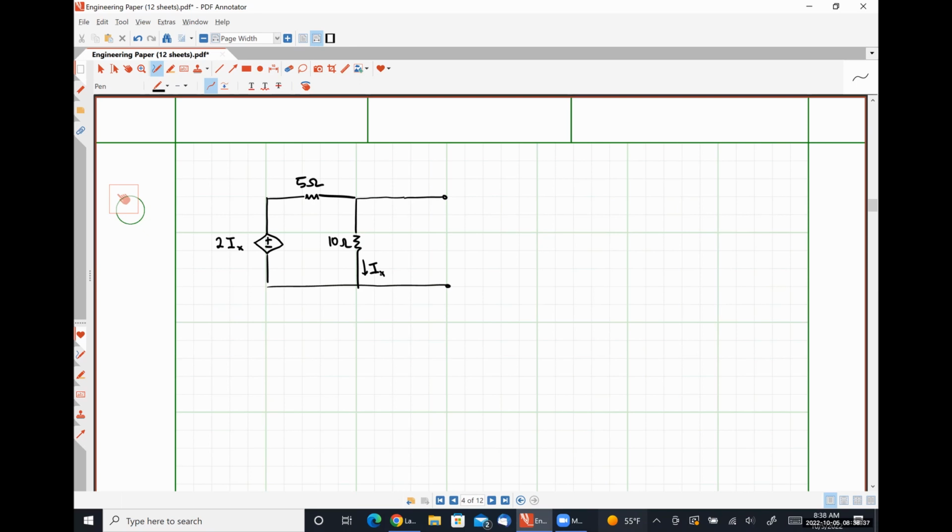So one thing that I would like to point out is that because this circuit does not contain any independent sources, the Thevenin equivalent voltage and the Norton equivalent current are effectively meaningless because we don't have anything exciting our system, okay? So if you're ever given a circuit that only contains dependent sources, the only recourse you have is to use one of the test source methods, right? So this is the type of circuit that I would argue choosing your particular type of test source can make this problem more easy or more difficult.